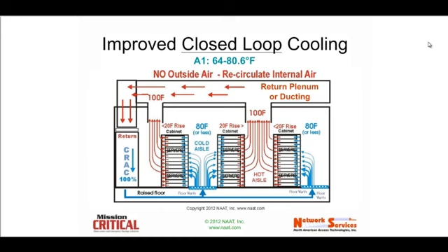We have no real opportunity in this particular drawing to show any free cooling. Also, I'd like you to take note of a typical condition where we're going to try to maintain within the ASHRAE envelope of 80.6, so we're looking at 80 degrees or less in the cold aisle. And we're using a typical 20-degree temperature rise, which obviously varies with the type of equipment, for the next few examples. So if all things were perfect, we'd bring in 80-degree air into the cold aisle.